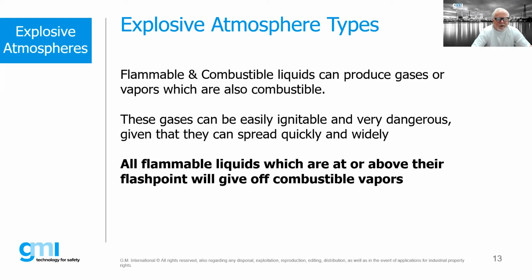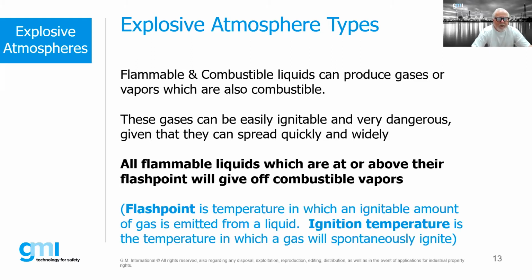You'll also hear a term that goes along with this called the ignition temperature of the gas. When we start talking about selection of equipment for hazardous locations, we have to be very concerned about the ignition temperature of the gases and vapors we're going to be seeing. The ignition temperature is the temperature at which the gas will spontaneously ignite. Those are two terms you hear an awful lot, and a lot of people get them confused.